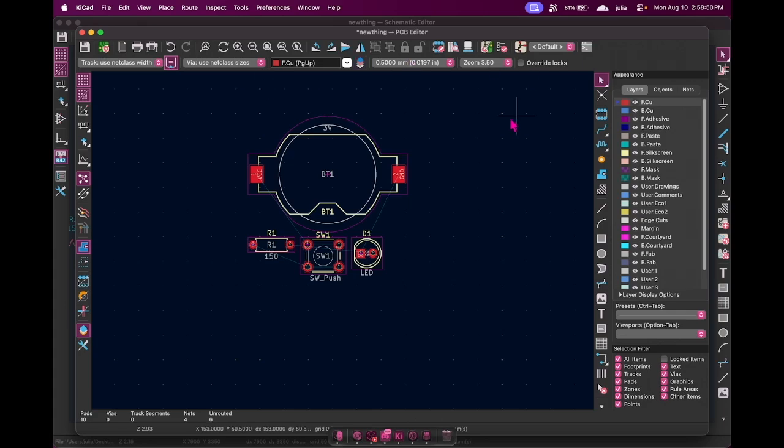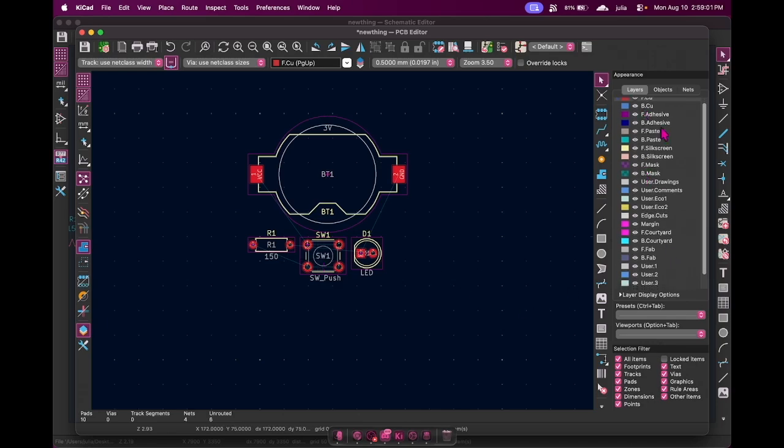Anyways, we're going to make our board outline, which basically says what the actual board is. Because as you can see here, there's no board shape. We just have our components. So what we're going to do, you can see multiple layers here. These are very important. You have to pay attention very closely to which layer you're on when you're doing this stuff. You make something on the wrong layer, it's all over for you, bro. Anyways, we're going to go on the Edge Cuts layer. That's where we make the shape of the board. You're cutting it at the edge.